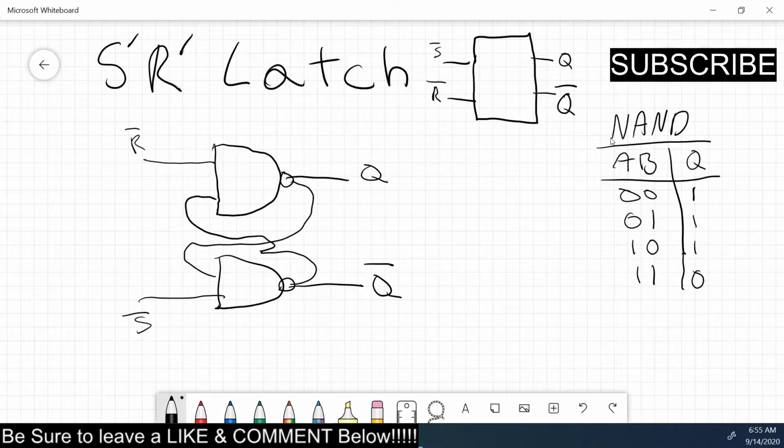Now the difference with using this gate is that with the standard SR latch, I pulled the inputs low. So these need to be pulled high, so these need pull-up resistors. So let's show you that in implementation, and then we'll look at how it works with the truth table there.